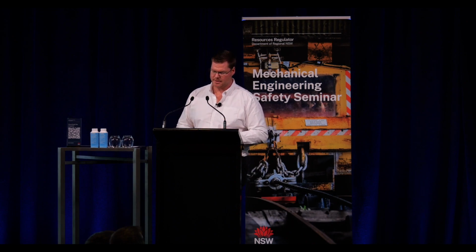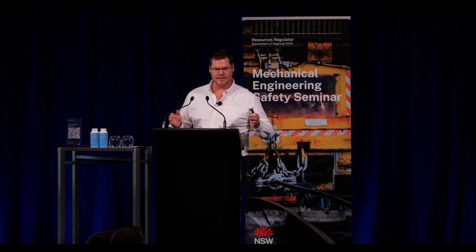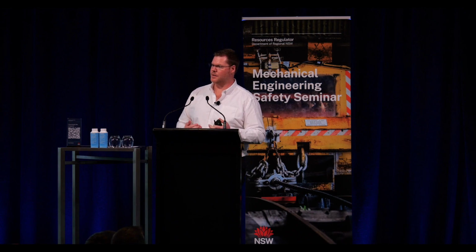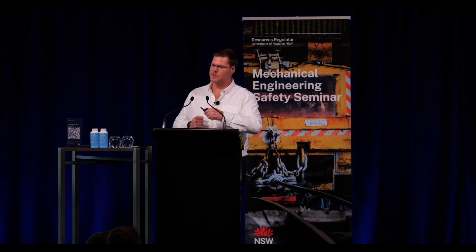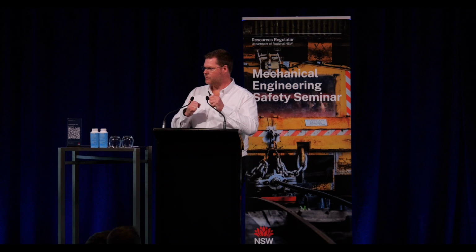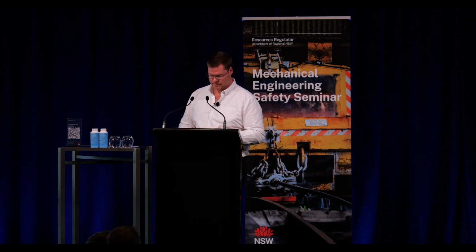Secondary reasons: you need to preload the rope so it gets to its actual operating diameter from its relaxed diameter, to make sure that when it's at its operating diameter, it is bunched up and all tightened, so there are no potential air gaps in the future. It's also there to prevent any slip between the rope and the drum, because if they are loose on the dead turns as you're putting subsequent layers on, you can get it grinding away on the rope and the drum itself.